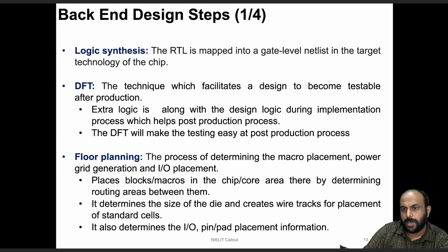It would be substantially different if you are trying to create a netlist for a field programmable gate array or some other programmable logic. So logic synthesis is a step which takes the design file RTL as one of its inputs. It also takes a user constraint file, which are the user given constraints of the design. Also, it takes a lot of library inputs. So the output of logic synthesis is a combination of all these three inputs.